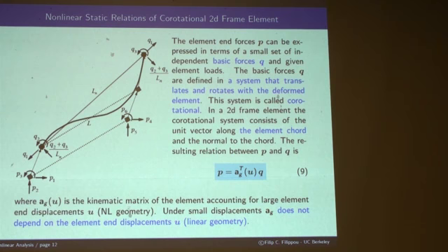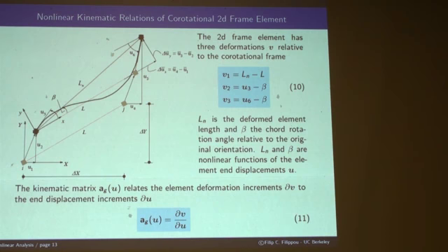All right, so here I'm a little sloppy. I'll try to correct this, maybe add another page and be a little more specific. I think this is a little superficial here. It needs a little elaboration. There is too little time to explain this picture, but essentially as the element moves in the plane, because it's a 2D element, the actual frame element moves in space, and we have large rotations and large displacements, and the large rotations are a pain, very hard to track.